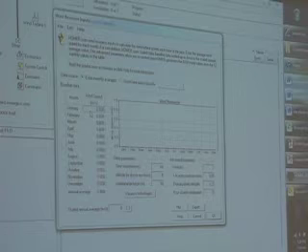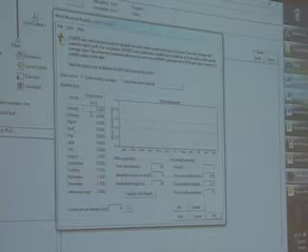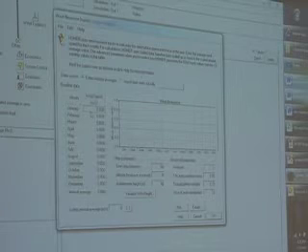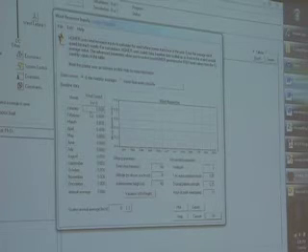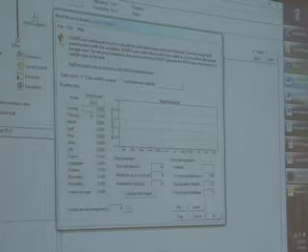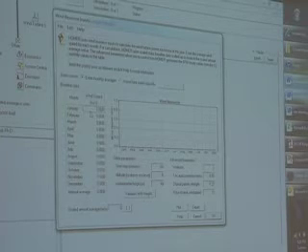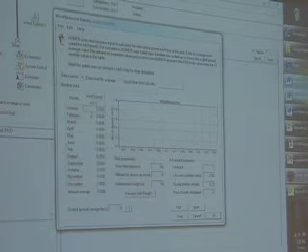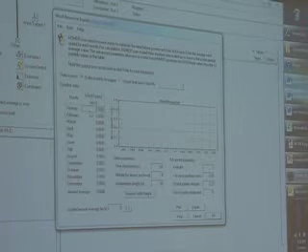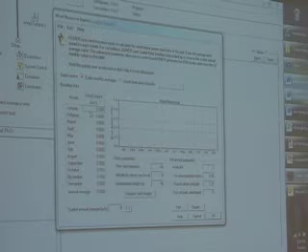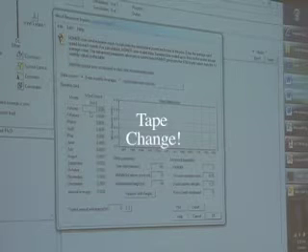So you can get seasonal data from lots of websites that'll give you monthly averages over the course of the year. The problem with the data that you find on the web, I use weatherbase.com, is it's airport data. It's from a 10-meter high anemometer. It's probably not above the trees. The magnitudes are going to be off.